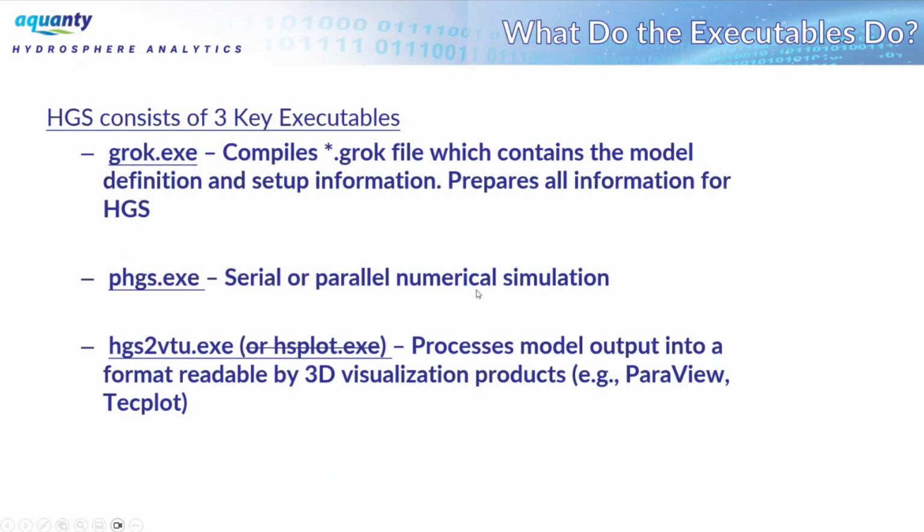So 3 key executables in the HGS workflow. grok.exe compiles the grok file. It prepares the information for HydroGeoSphere. phgs.exe is the actual numerical simulator. This really truly is what HydroGeoSphere, the simulation engine, is.